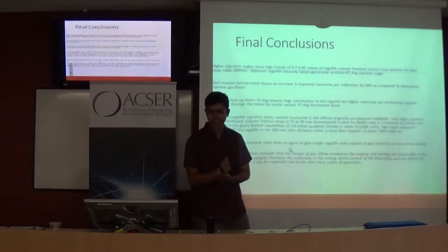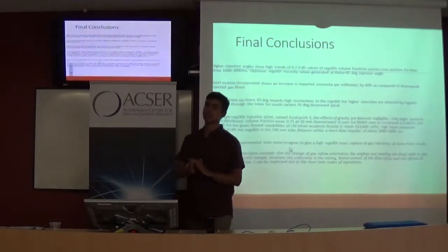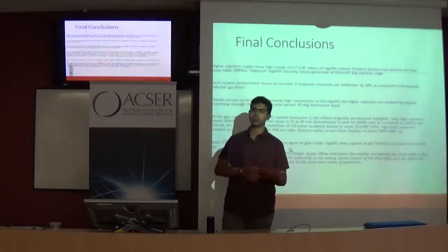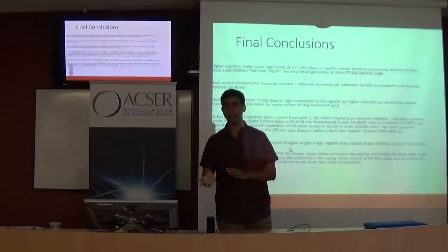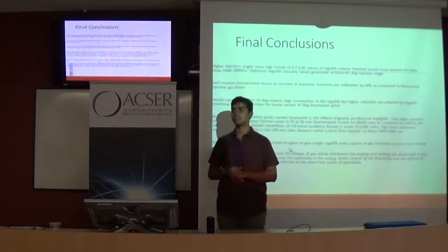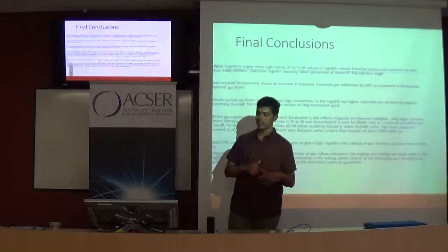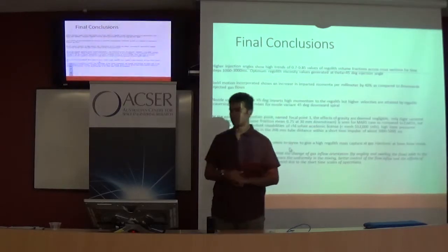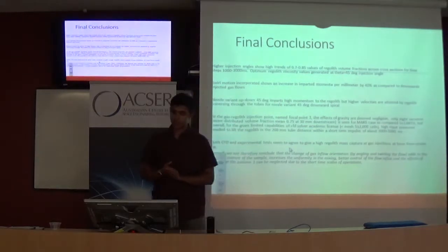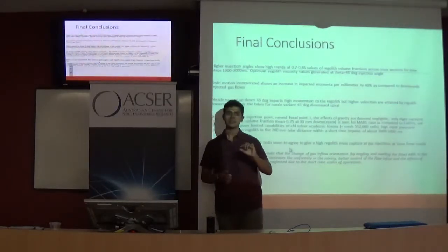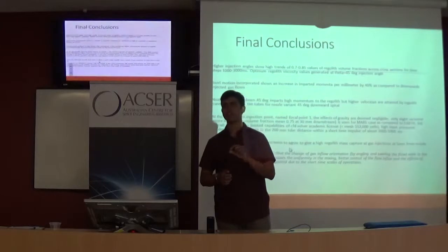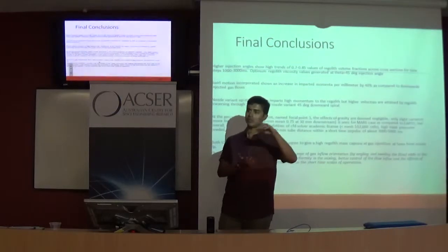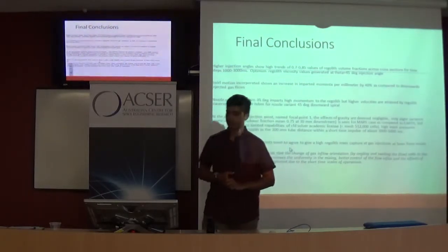So the final conclusions of the work were that yes, swirl and angle assisted flows eventually do lead to better capture of regolith. This is being looked into now in a much better way, as we are trying to do some more tests within a vacuum chamber in Pasadena and see if we can achieve the values which my model had got for different temperature and pressure environments. And the optimum depth to which the lander foot leg needs to be penetrated is about 5 centimeters for this particular case. That is another thing that I was able to get. I was able to measure it up and down and see at what level I was getting the optimum value.